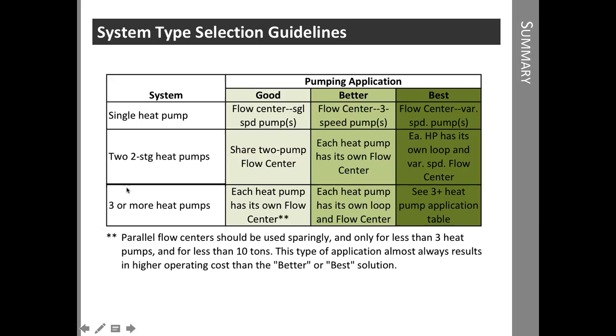When we get into 3 or more heat pumps, you could certainly have a flow center for each heat pump. We just have to be careful if we're using these on a common loop because of what we looked at earlier with that parallel operation, higher watts, of course, and we also have to typically upsize the pumps because of that parallel operation.